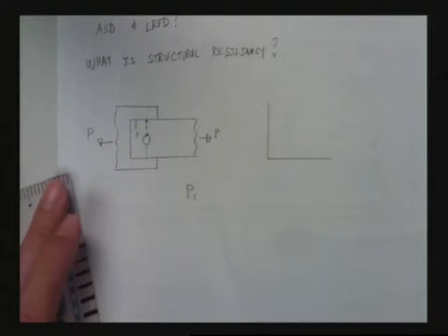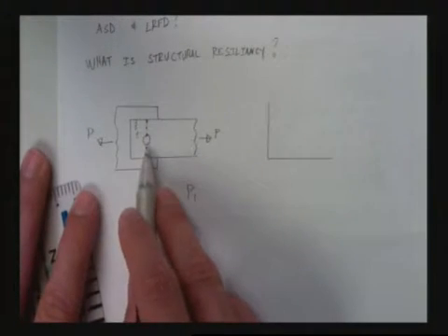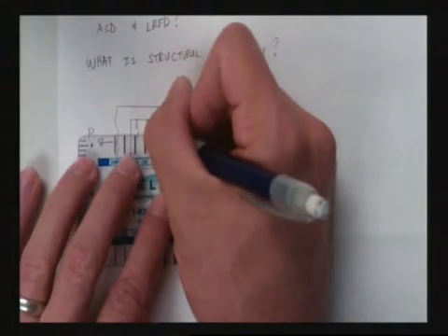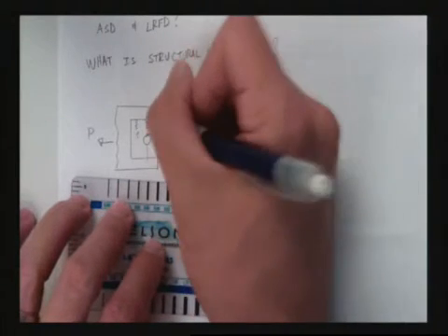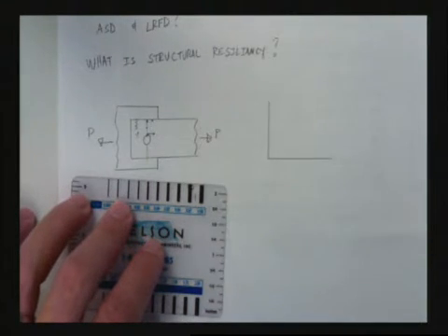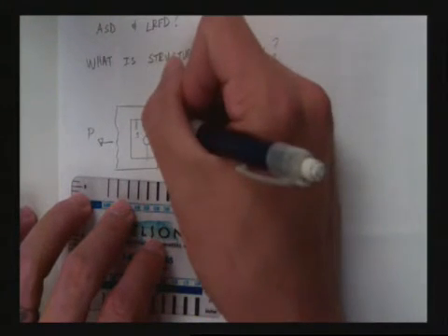Why not? Got a stress concentration at the hole. That's exactly right. And stress concentration is going to cause localized stresses to increase. So right here, locally at the hole, we would expect to see this part higher than this part. Now what's it look like in between? No one really knows, and no one really cares either. It is going to look nonlinear.